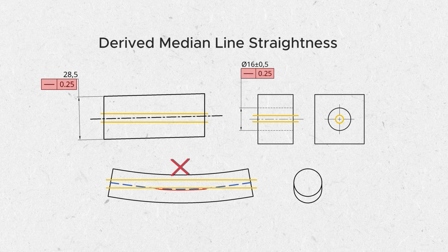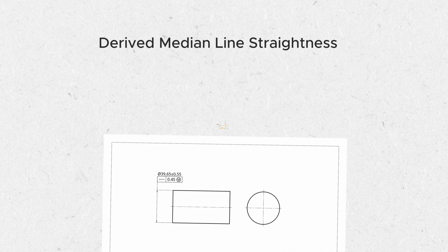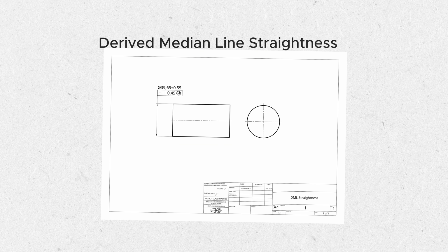This is especially important for rotating parts, bearings, and precision assemblies, where any deviation in the axis could cause vibration, misalignment, or uneven wear. On a drawing, axis straightness is called out next to the size dimension of the axis, and to gauge axis straightness effectively, the MMC modifier is sometimes called out on the drawing.